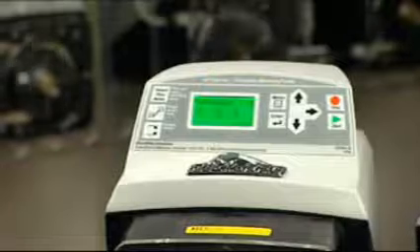Now we'll configure the secondary pump's input signal. Enter the Input Setup menu. Then the Input Modes menu, and then select 4 to 20 milliamp input. Input a milliamp value of 4 to define a low point on the slope. Input the value of 0 for the percentage of speed required at the low milliamp value.